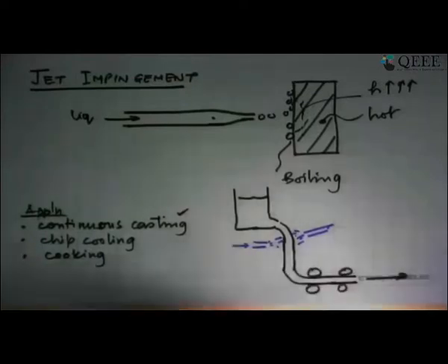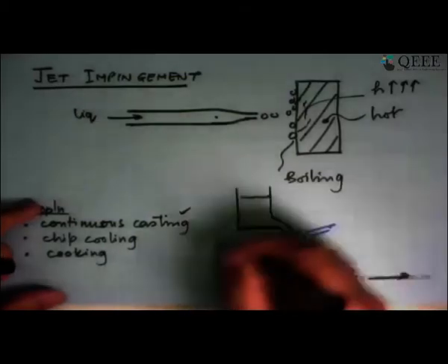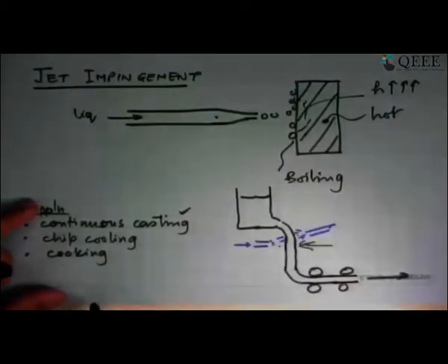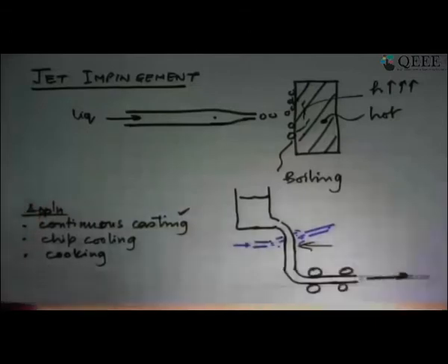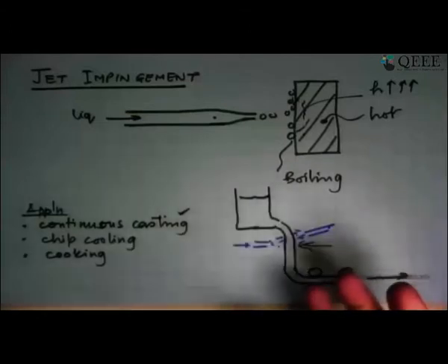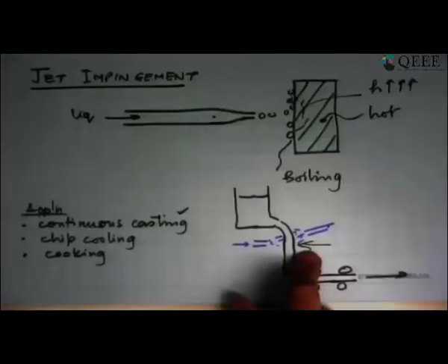But the big breakthrough that happened in this was the understanding of impingement boiling taking place at the surface of liquid steel. And what it did was to revolutionize completely the entire technology of manufacturing steel. It requires significantly less energy per ton than what the older process required. It is hugely automated. It requires very few people to operate it. So the productivity of the steel plants increased by a factor of 10, and old steel plants just had to die. They could not compete with the steel purely because of these two reasons. And at the heart of that was our ability to understand jet impingement boiling.